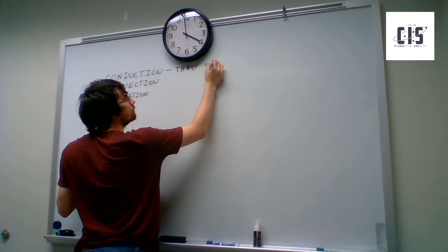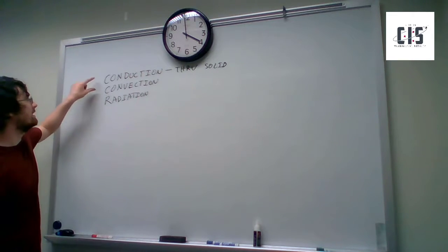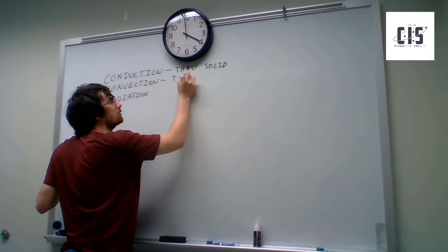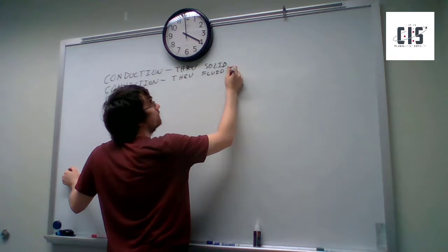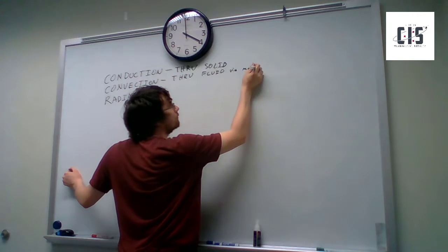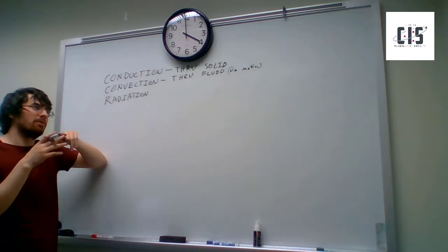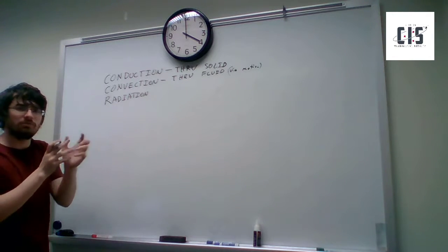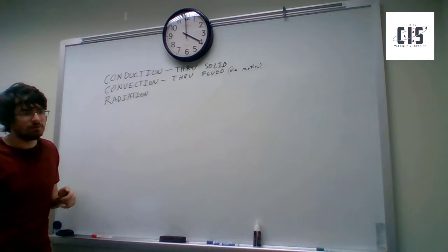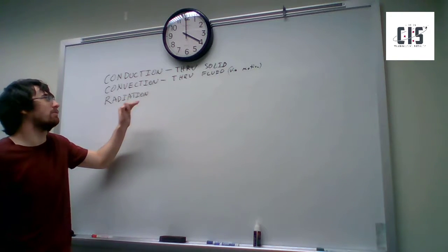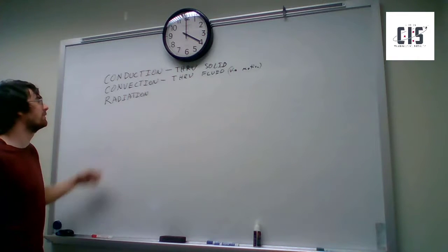Would a medium like glue or some other binding agent count as touching? It can be. It's going to be a mixture of that and convection, which is through a fluid. So it's important to recognize that if nothing in the fluid is moving, so if it's a glue and the glue particles aren't moving around too much, then yeah, it's just conduction. But convection is fluid motion that causes heat transfer. So technically, convection is a type of conduction. But it's just a simplified model for gases and liquids because trying to do conduction models with that sucks.